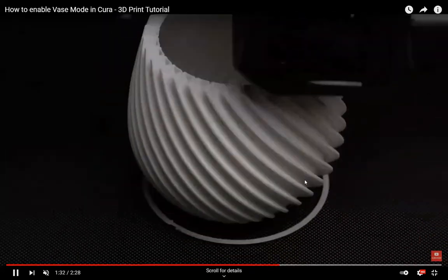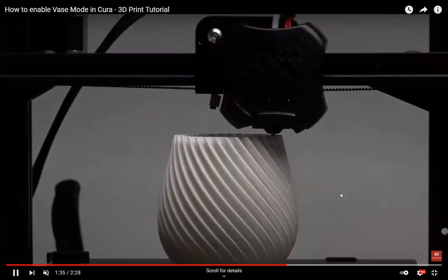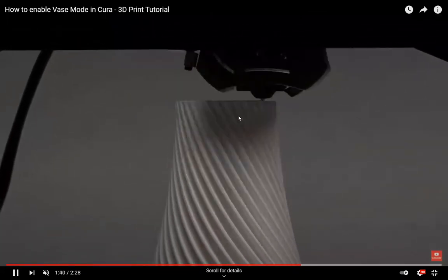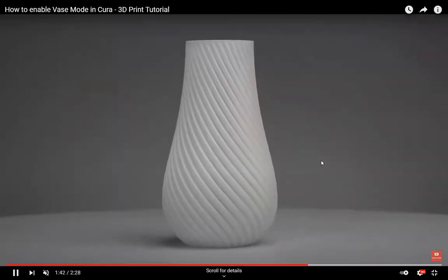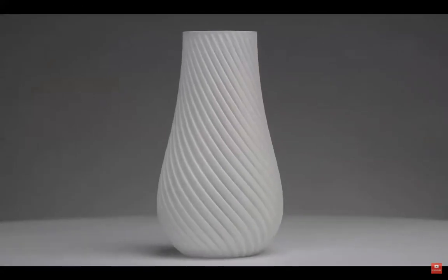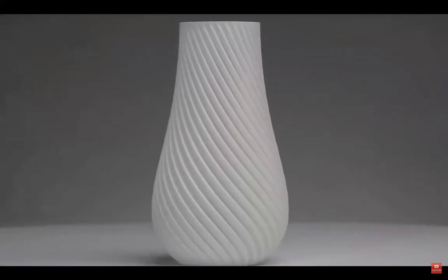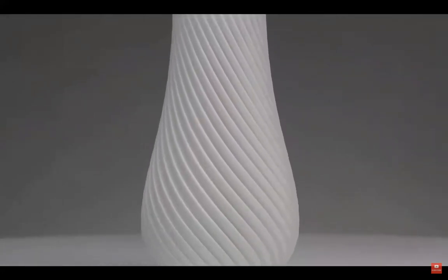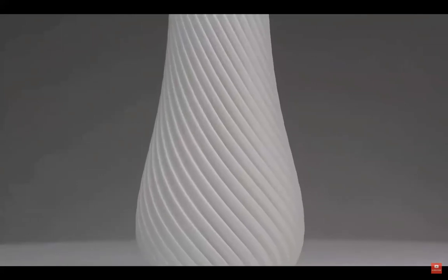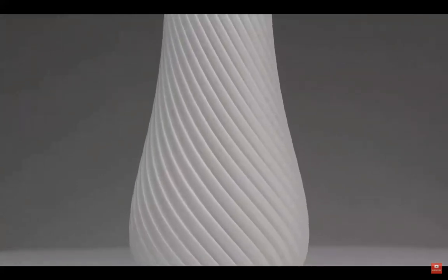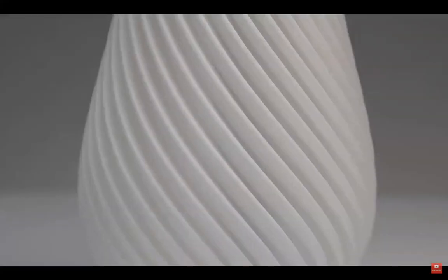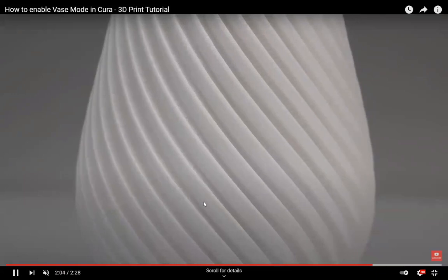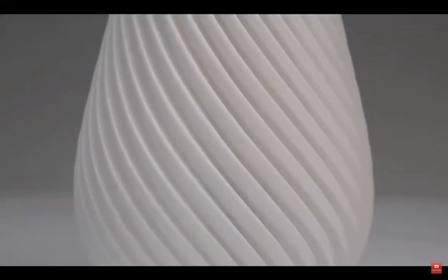When you see this right here, what they're using is a program called Octoprint. And what it does, at least what I think it is on this machine here, on this video, is that after every layer, it parks the head in the corner, the print head, the print nozzle, and then it takes a picture. So it's a very slow process because it slows the machine down by about 20 seconds per layer. But the videos look incredible because you get this complete build volume, which might have taken 7 or 8 hours, in about half a minute.